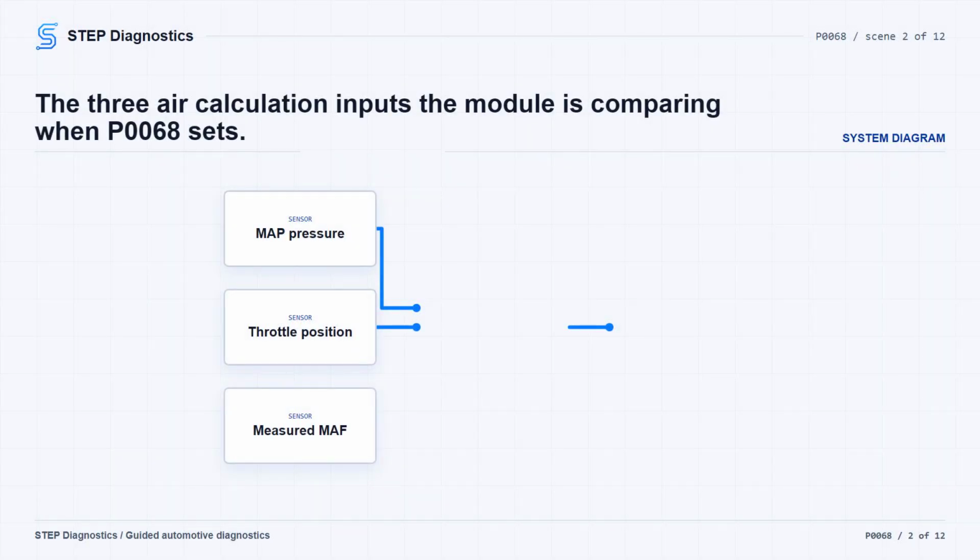light on. Possible fault areas often include air leaks, intake restrictions, throttle body condition, MAP or MAF signal behavior, connector issues, or an engine or exhaust condition that changes the airflow calculation. Start with the basic system checks, follow a structured diagnostic approach, and keep the diagnosis aimed at proving which part of the air calculation is not believable.